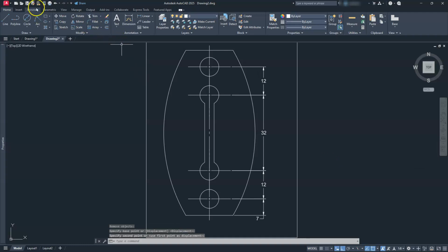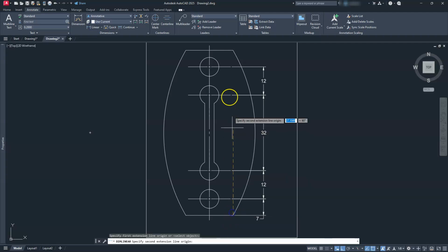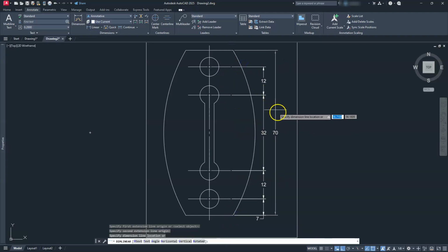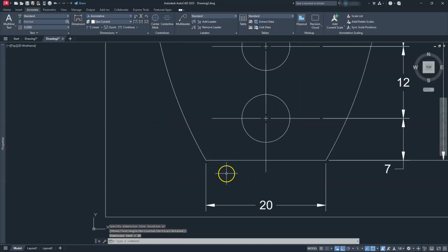All right. Let's go ahead and finish this up with some more linear dimensions. A linear dimension from here to here. Let's do the ones here at the bottom. So I have a linear dimension going from that endpoint to this one. And once again, I want to verify and make sure that if this 10 is going to kick out, it's going to kick out to the outside. So I'm going to select linear, this endpoint to this endpoint. Okay, it's good enough for us that it stayed on the inside.